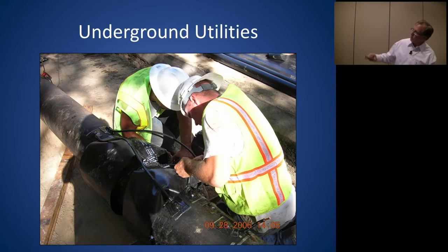Hopefully you guys can see these better than I can. There's a glare up here, but this is what the joint bonding looks like. This is a ductile iron pipe bond, or joint. We put bond wires across it so it's electrically continuous, then they put a shrink wrap coating around it. That prevents those holes in there that you saw in one of those earlier slides.